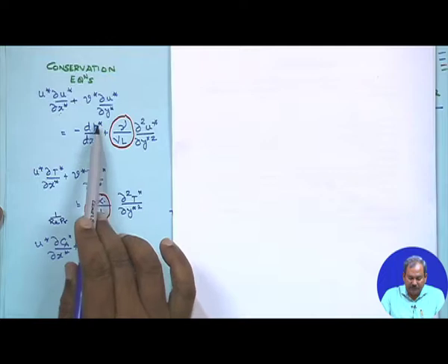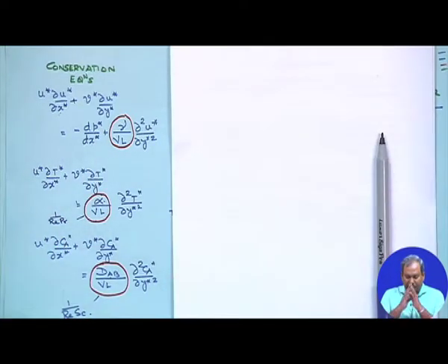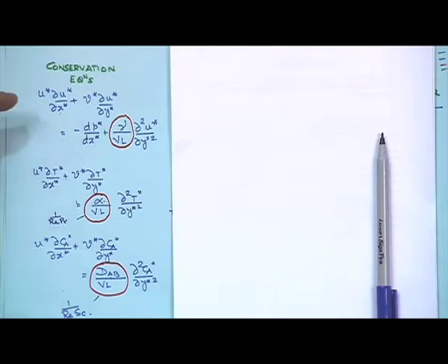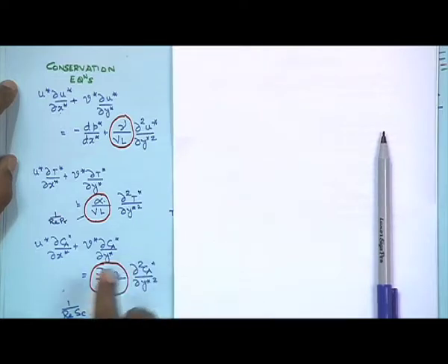for the case where dp dx is 0, that means we are dealing with a flat plate. So, think about the implication of our assumption here. I would like to make these three equations identical. All are going to have an advection term on the left and a diffusion term on the right.